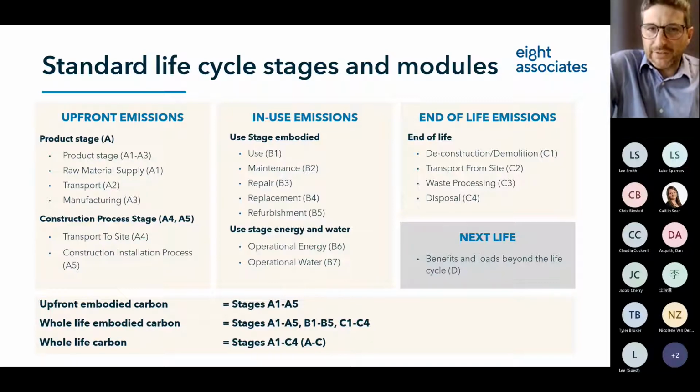But it's recognised, obviously, a lot of materials can have a second, third, fourth, fifth life, and that's captured in this module D. So you can show, based on current practice, how much the benefit of a material that can be used in a second life. And it's not something you add on or you minus off of the total for the life cycle of the building. It's just reported as a separate bit of information. You can also have what are called loads, so negative, unwanted effects in that stage too.